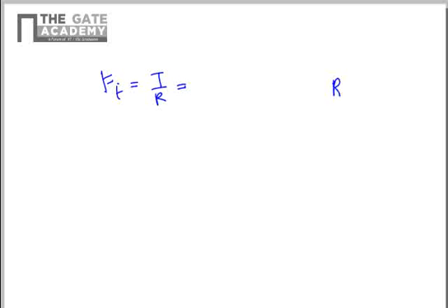For this we need R. R can be determined from the module, since module is equal to d by t. So 2R is equal to m into number of teeth, so R is m into number of teeth divided by 2. Module is given as 6.5 and the number of teeth is 40, divided by 2.